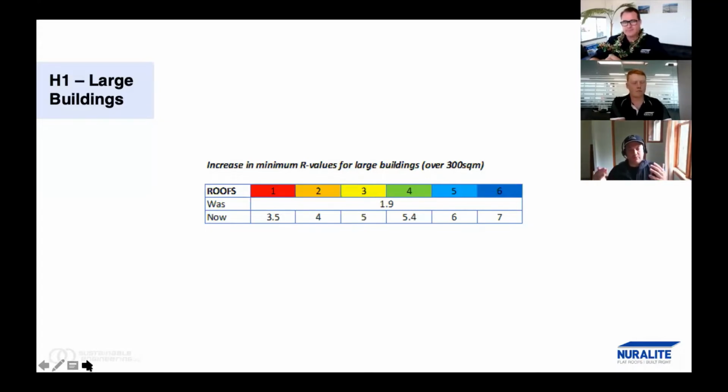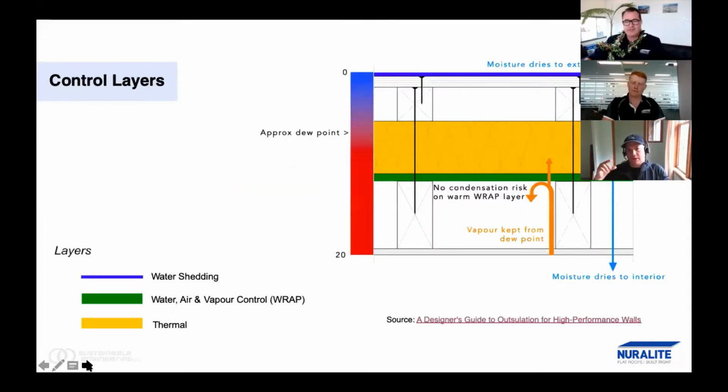So our most common construction, the one that MBIE probably had in mind when they laid this out, was a vented attic roof, or what Peter typically calls a cold roof assembly, where you've got a gypsum board ceiling or some other nice air control layer in the ceiling, and you've got insulation on top, and then above that it's ventilated to outside air. So the important thing, and the next slide is a good one to get into, is it's all about keeping that warm, moist air from getting into that attic space or above the insulation, because once it does that, unless it vents out very quickly, you get condensation.